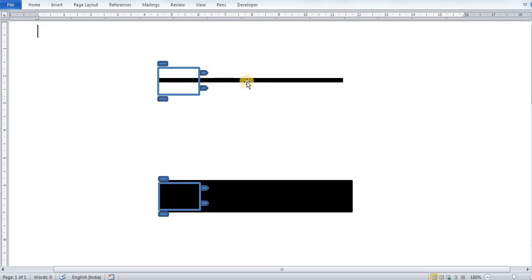Now in the thin line variant, the black line is in between these 2 sensors. And so that means we are traveling correct if both our sensors are reading the white value.